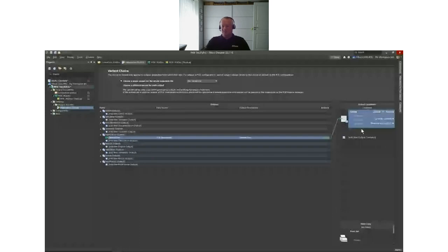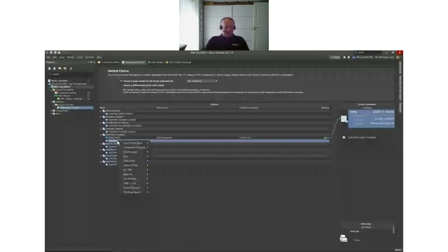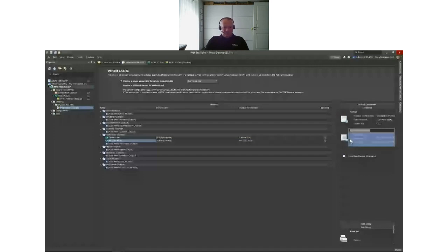And make this one the connection here. If I then generate the content, and normally when you generate Gerber data for a normal PCB, you will also need to create drill files, NC drill files. But in this case, we don't actually need to drill, so we don't need the files, in my opinion at least.